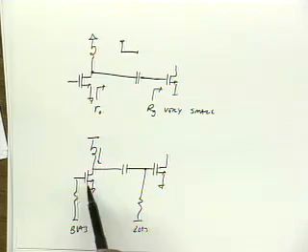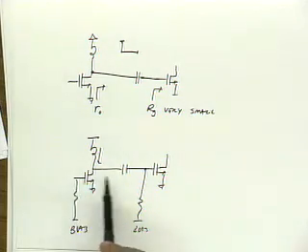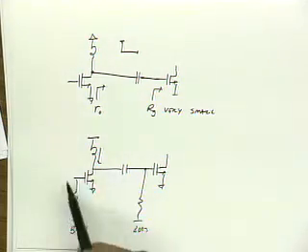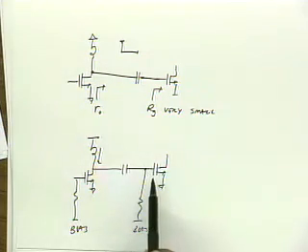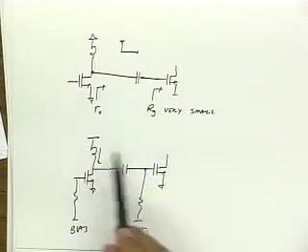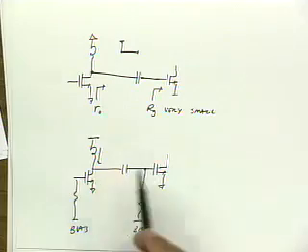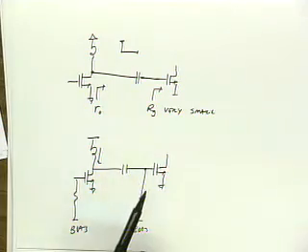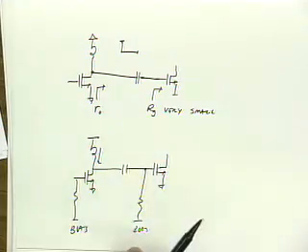Well, the downside, though, is that what if we wanted to low-pass filter the output of this guy before it drives the second stage? This is doing the opposite. It's high-pass filtering. In that case, we would use the other termination, but we'd end up having to put in a lot of extra elements.